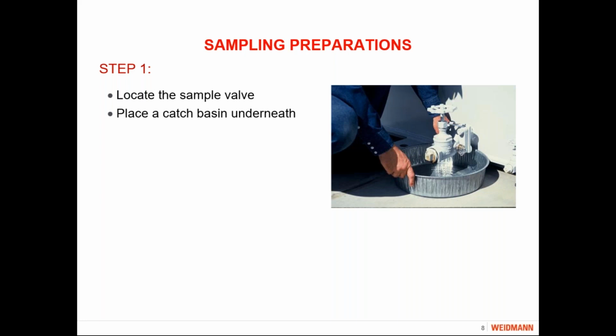Before you do anything else, you need to put some kind of a catch basin underneath, because you're going to be pulling some oil out, and you don't want to be spilling that onto your foundation or onto the ground. That's generally an environmental hazard, and it's something to be avoided.